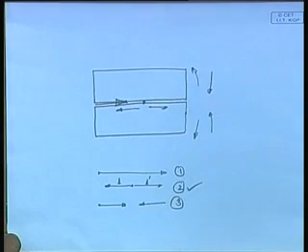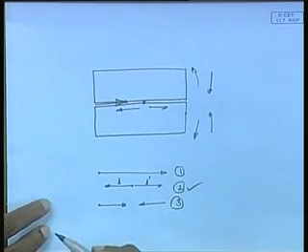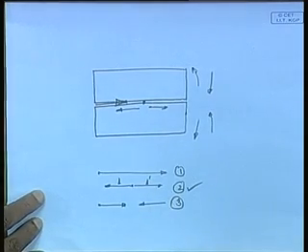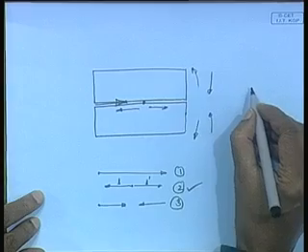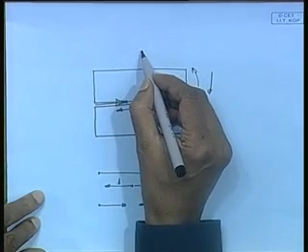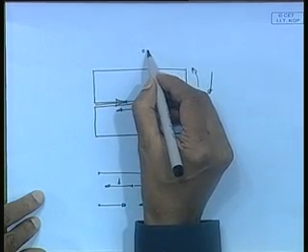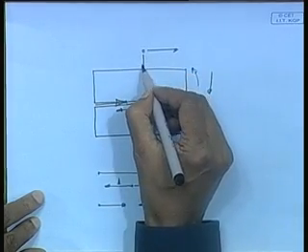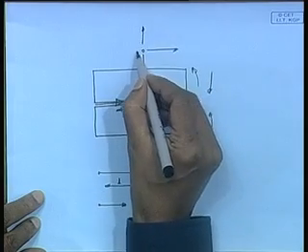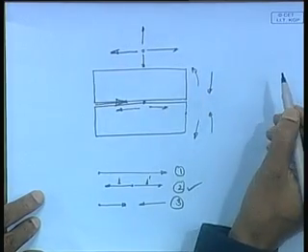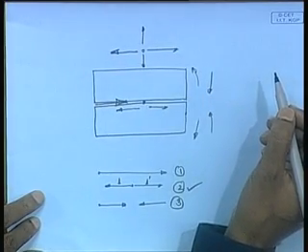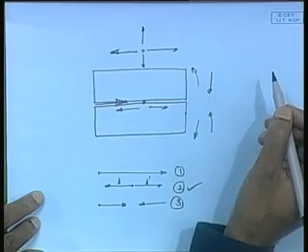This is a very simple case of butt welding, and the general rule is weld outwards, always welding should start from the center and go outward. That is the general thumb rule while designing a sequence of welding: the welding process should start from near the middle of the structure and go outwards.